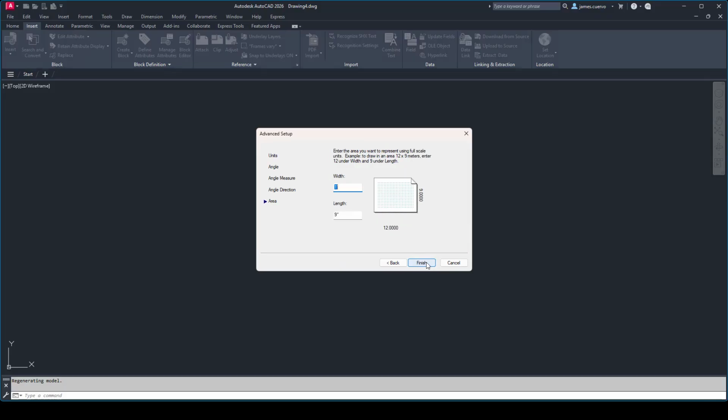I would usually say, why don't you go ahead and use the size of the sheet that you're going to be using, and then just go ahead and do your scale factoring to that. So if I'm using a 24 by 36 at 1/4 inch, we're looking at 144 feet by 96 feet. So the foot value is what I would put in here. Okay, be aware of that.